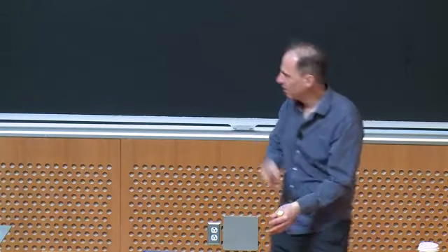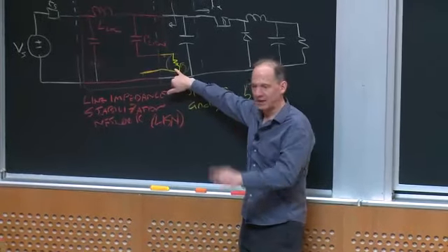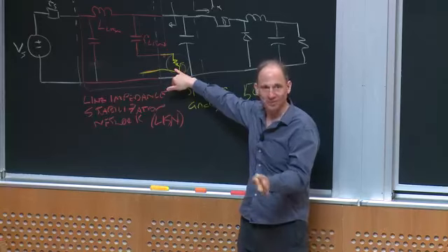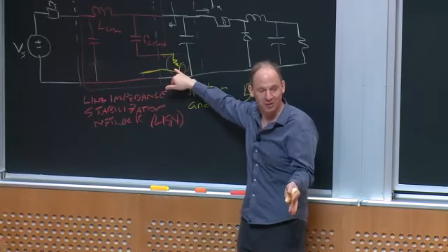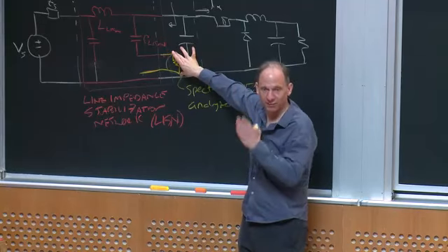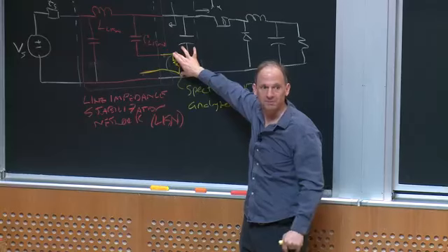And the way the specifications are read is for conducted EMI, you'll look at this response, spectrum analyzer configured a certain way with certain kinds of quasi-peak or peak detectors. There's a whole bunch of rules around it. And you're generally measuring the energy in different frequency bands and seeing do they go above an allowed limit.